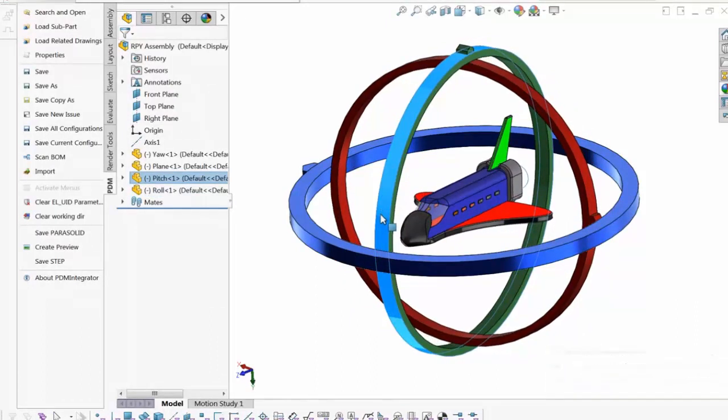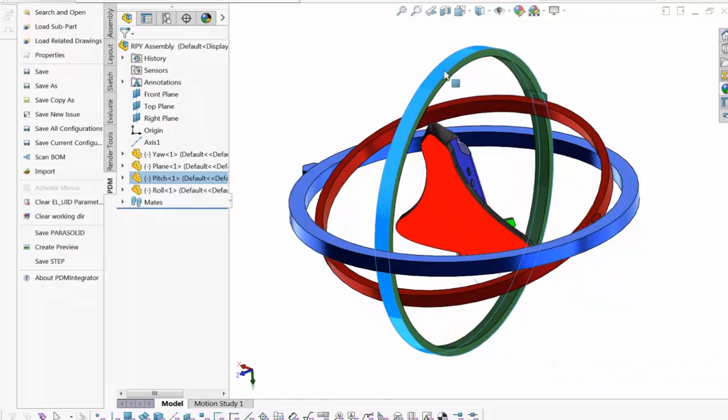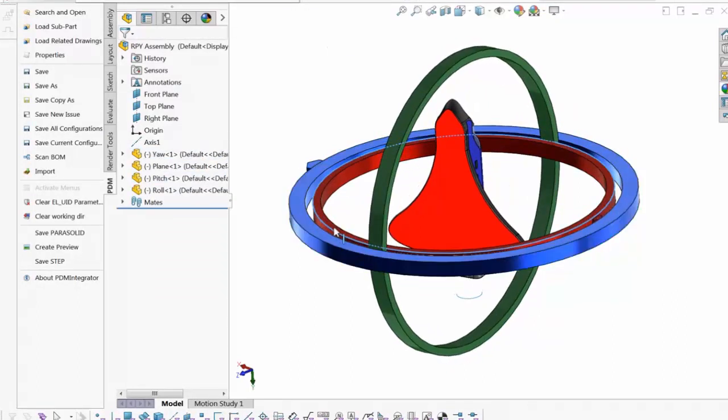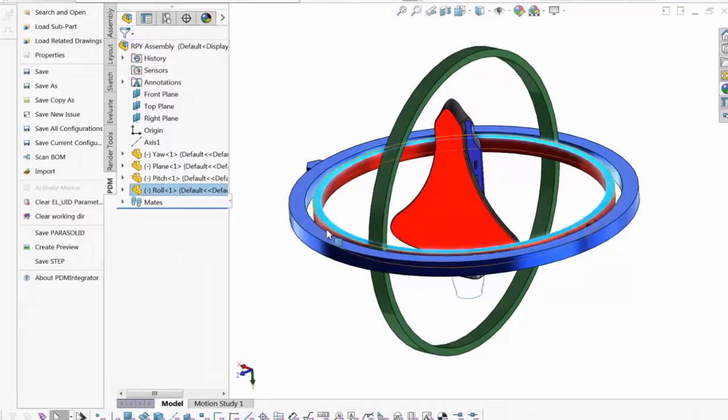The challenge with the Euler angles, the biggest problem, is right here. If that middle angle gets to 90 degrees, I have aligned the yaw and the roll axis, and now I have two ways to create motion, and it doesn't know how to solve it. The other problem that this creates is because I've combined these two rotations, I get this gimbal lock, or singularity, it's called. If you imagine you were in this ship and you wanted to turn right or left, there's no degree of freedom to allow me to turn right or left. So the gimbal lock basically combines two rotations in the same direction and removes a third degree of freedom that you want to be able to rotate.